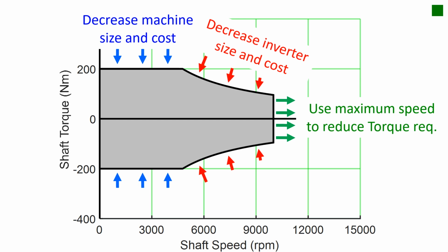Have we found the perfect electric powertrain? Not necessarily. We have found a reasonable electric powertrain with a low cost for the electric machine and the inverter. But since there are other factors besides minimized cost, there may be reasons to also analyze other ways of sizing the powertrain. Now you have learned a method to size a single-speed electric powertrain to meet a certain set of requirements at a low cost.